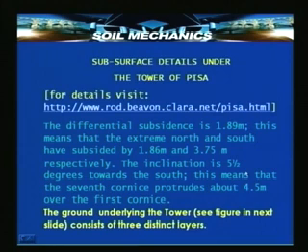The tilt that took place because of this is 5.5 degrees towards the north, because the north has subsided more. This means that the 7th cornice, you know, there are several levels, protrudes about 4.5 meters over the first cornice. That is the amount of lateral movement that has arisen because of this settlement.